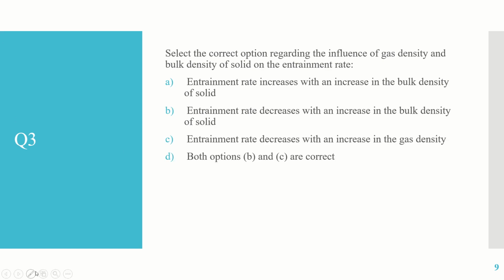So what happens is that the carryover capacity of the gas is reduced with higher density. So entrainment rate decreases with an increase in the gas density. Similarly, entrainment rate decreases with an increase in the bulk density of solid.